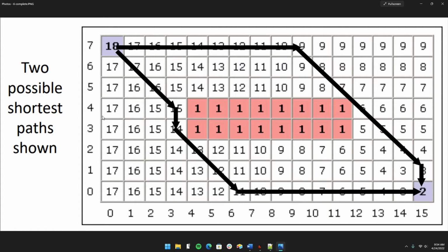One, since my robot isn't going diagonally through any cells, it uses the 4-point connectivity rather than 8. So the neighbors are only the cells that are up, down, left, and right of it. And 2, I'm using a 9x9 grid to represent the maze that we have. So for this example, the grid has 2 shortest paths, and with some of the test cases I run with my robot, my algorithm just picks whichever one of the paths randomly and sends the robot to go through the motions. So let me show you that now.